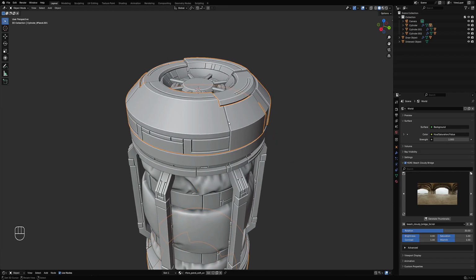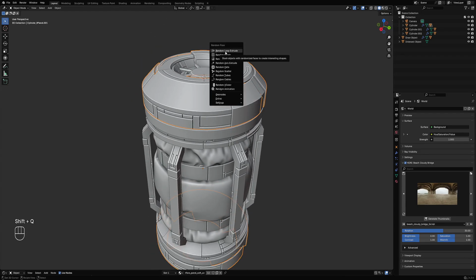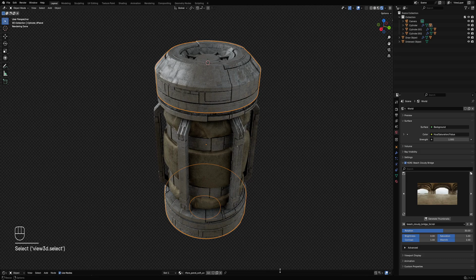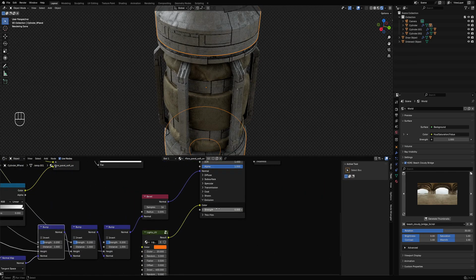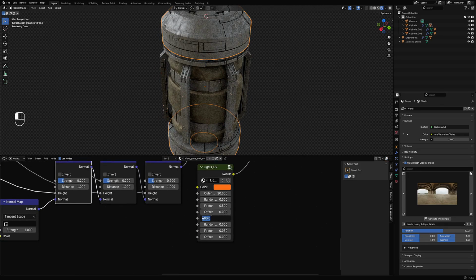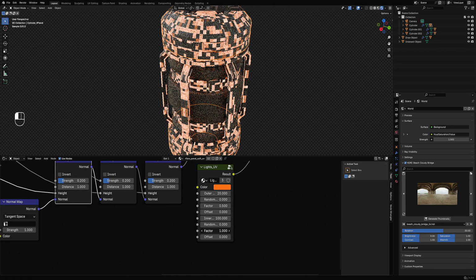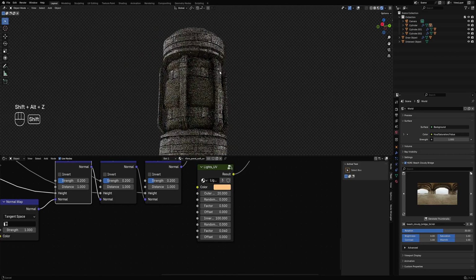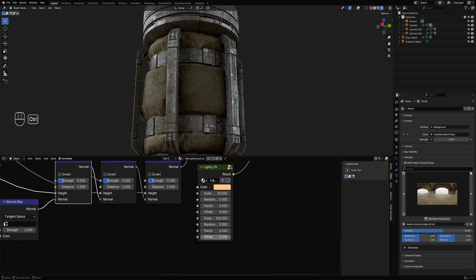And this is besides it being primarily created for random extrude and random panels. Okay, so we can again activate the lights by doing that and reducing the scale. The factor affects the number of lights, and then you can just play around with the color. And the offset is the seed value. This is the W parameter in the shader.